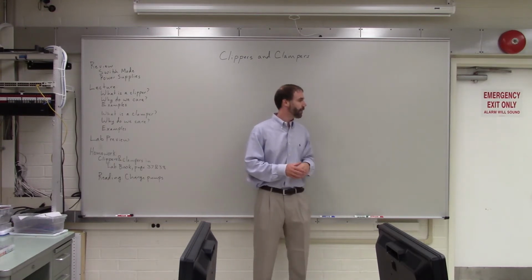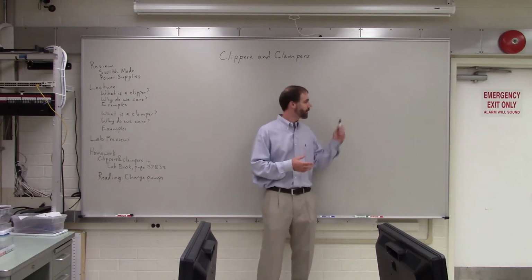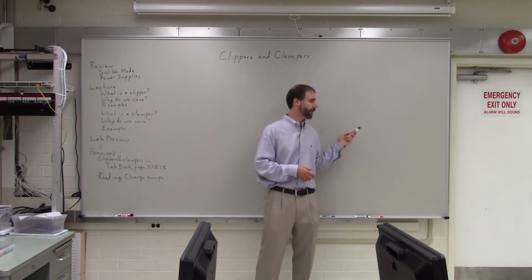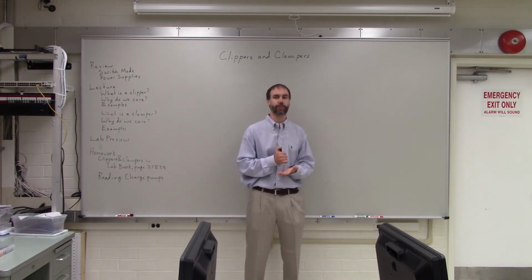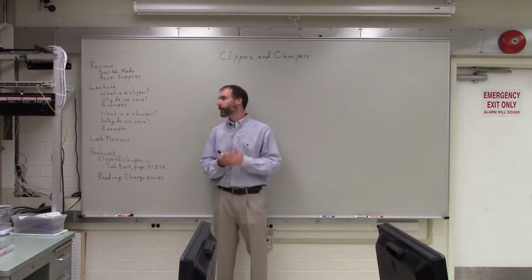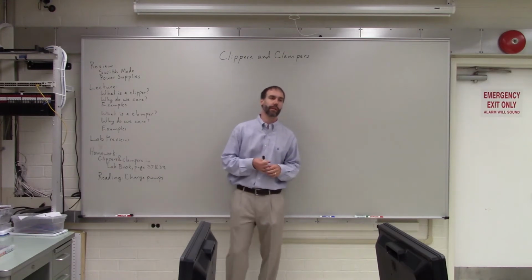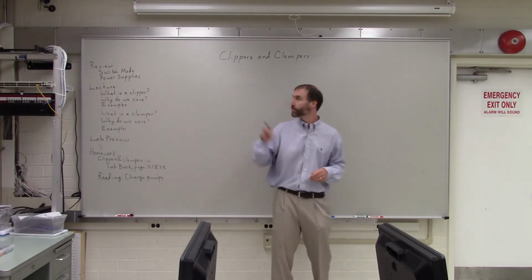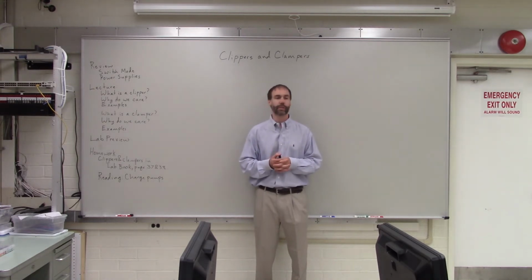So the one we built in the lab was essentially a DC regulator, but instead of being an analog regulator, it was a digital regulator. It was only on and off, so it again had that higher efficiency that we're looking for. Okay, so switch mode power supplies were very efficient when they run, and they're smaller and cheaper to build than analog supplies. So that's why a lot of power supplies are switch mode these days.